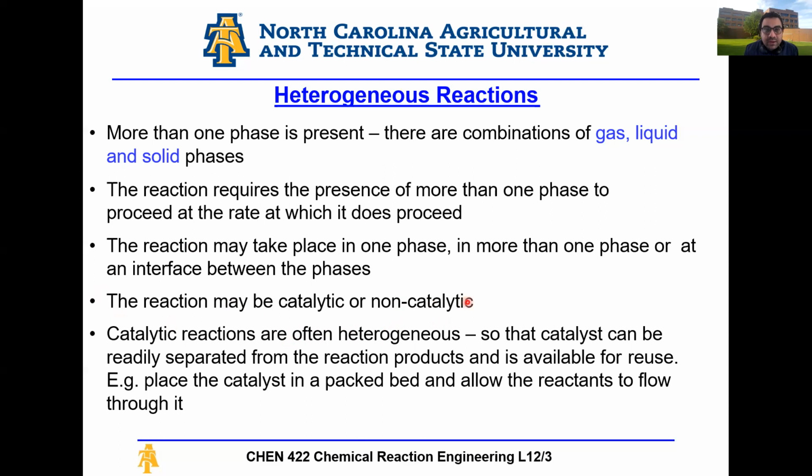One thing that comes to mind is using MDEA or MEA, an amine, for stripping H2S or stripping CO2 from a natural gas feed. This is a chemical reaction, and it happens readily. You don't have a catalyst there. Just introduce the gas and the liquid to each other, and your MEA or amine eats up the CO2. They form a carbamate, which is an intermediate chemical, and eats it up basically from the gas feed.